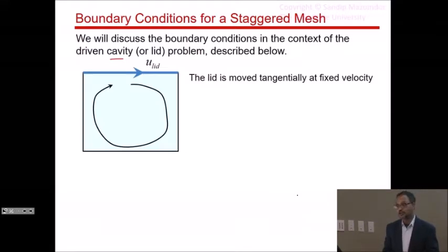All your governing equations will have extra terms due to the moving mesh. So your continuity equation won't be d/dt of rho plus divergence of rho u equal to 0. There will be another extra term which accounts for the change in volume. So keep in mind that this is a moving boundary problem. The case I mentioned, where the lid moves normal to the surface, is a special class of moving boundary problem, where the mesh itself has to move.